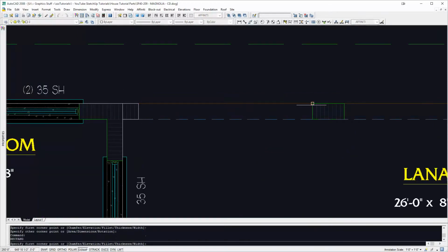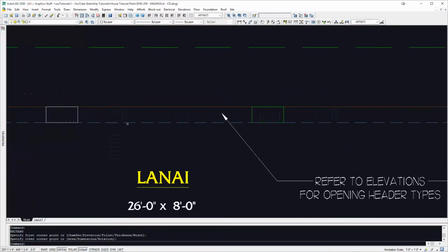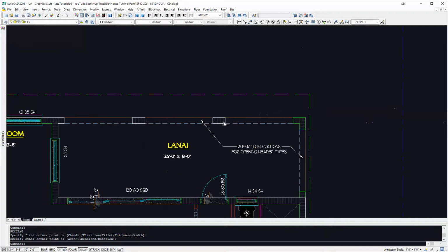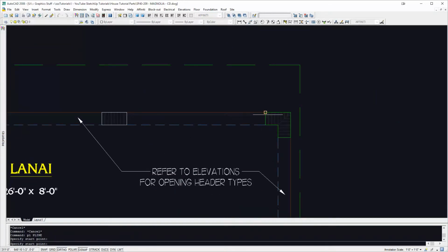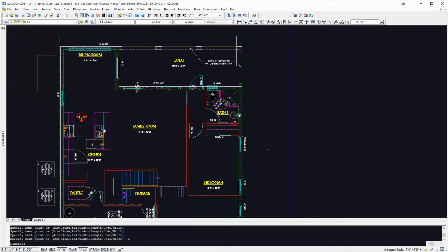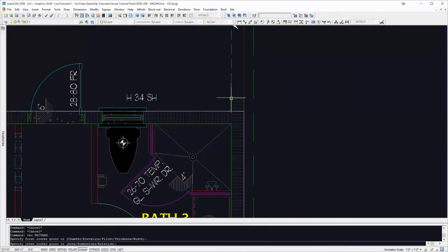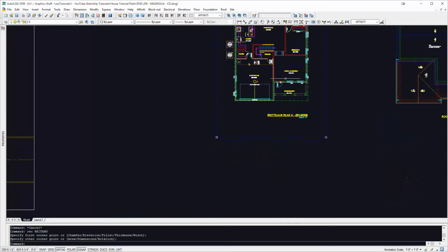For the first version, where it's just simply a wall that we're going to punch out holes, we can again just draw polylines around the columns and extrude those up, and then we can modify them within SketchUp to get the arches.